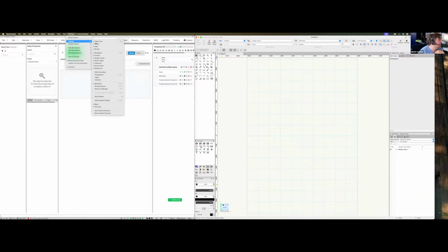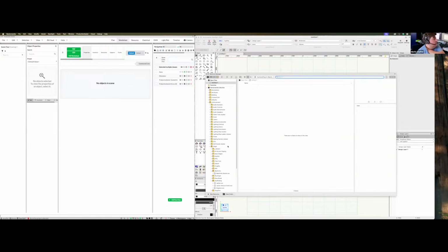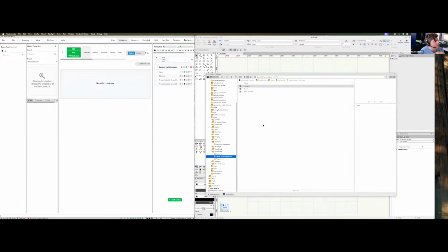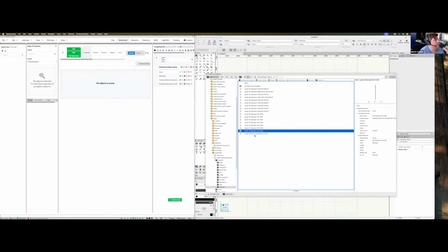So let's go into it. The good thing, and I hope this works today, is that you can just use the default library that comes with Vectorworks. I go to the Vectorworks library, I go to the entertainment folder, there's a folder called stage, and then there's a folder called layer and layer all around. We will start with the around stuff, and I click on this. We will start in a really simple way so that you see how this works and what is important to get started. So we need the standards element, and I use the 4 meter standard that we have.